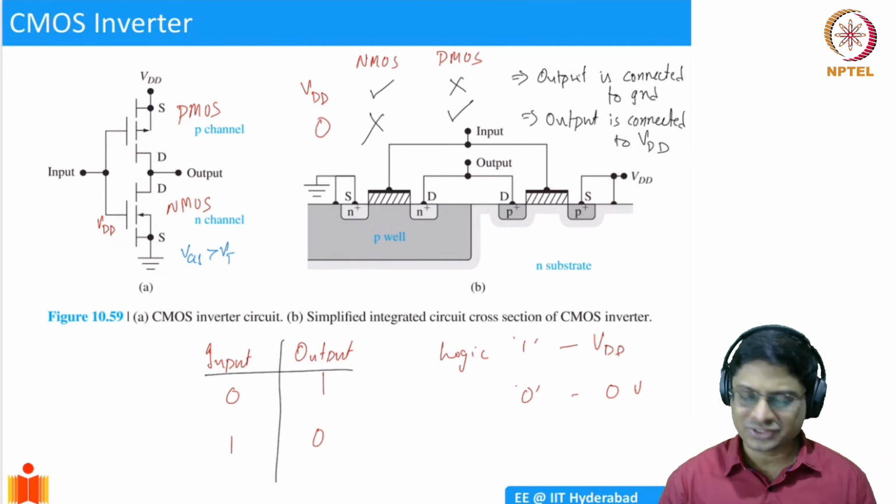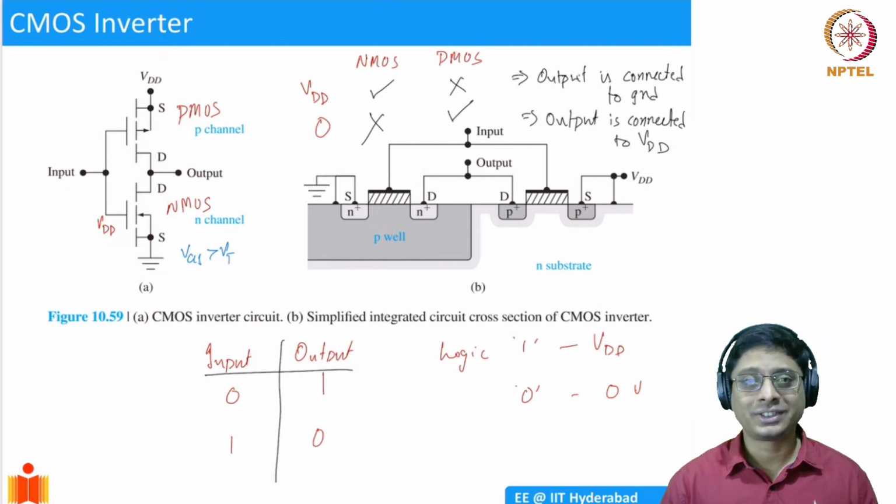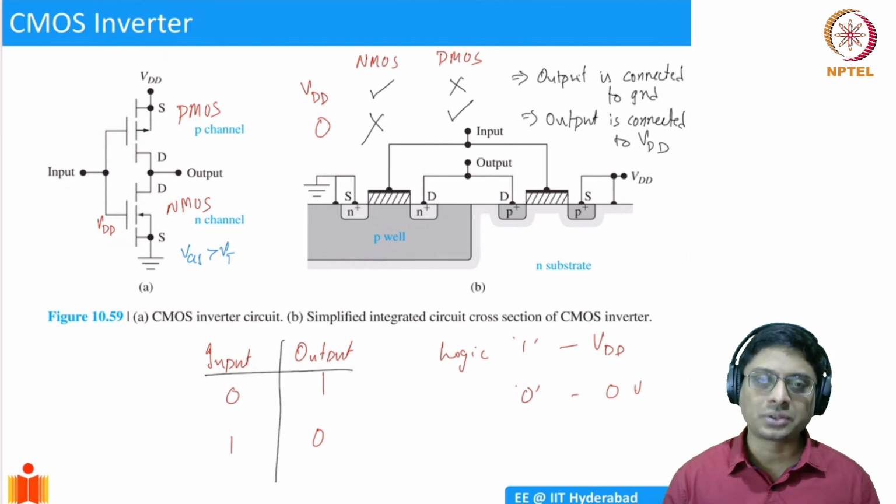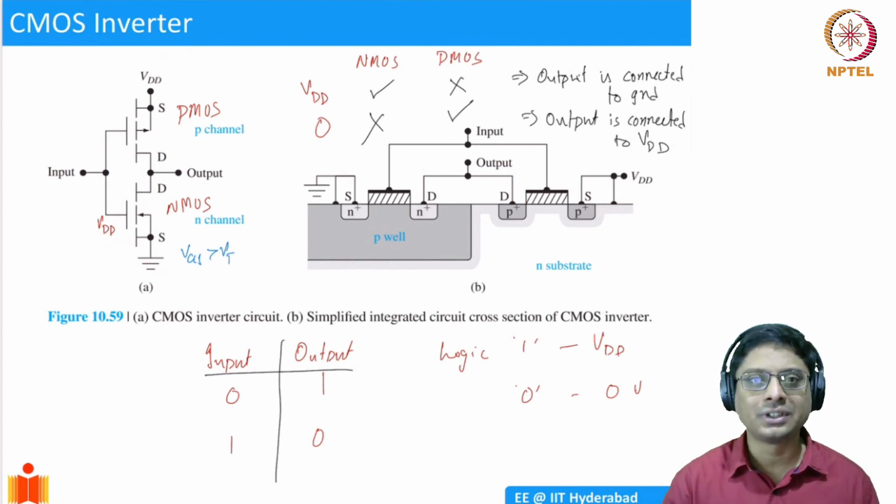So this was just a quick overview of what CMOS can do. We can design CMOS logic, NAND gates, NOR gates, and so on. That's another course on CMOS design that can also be taken, wherein you understand how to make NAND gates and NOR gates, what the trade-offs are, how you choose the width to length ratio of these structures, and how you design them. All that is an additional course on CMOS VLSI design from the transistor perspective. Of course, we will not cover that in this course, but that is something that you will learn at a later stage.